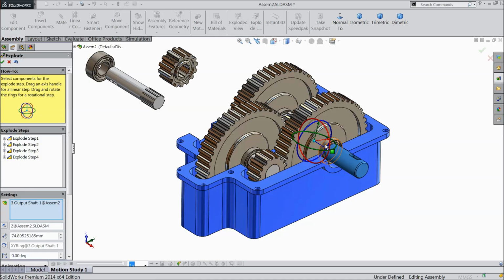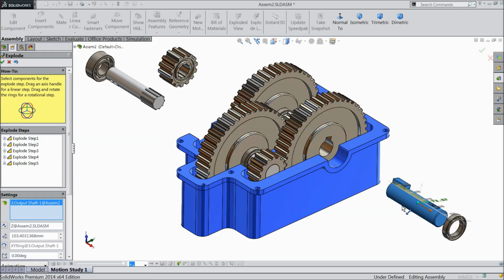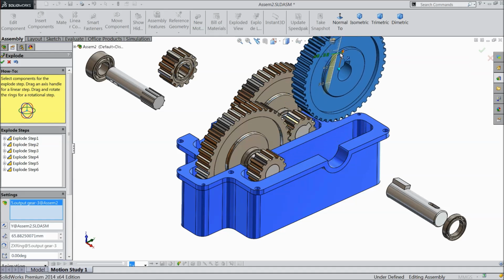Undo, better select first bearing out. Just select undo and clear here. Now choose bearing, shaft, then select gear. Of course the gear will go up, again select the gear.